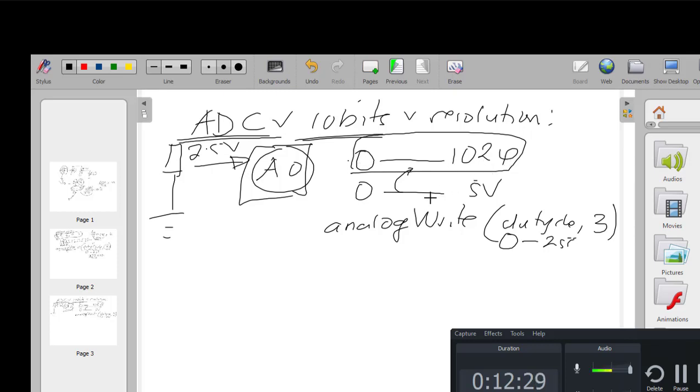So when we are reading from A0, we could read a value that is way beyond 255, which just doesn't work correctly for our duty cycle. We may get out of range.